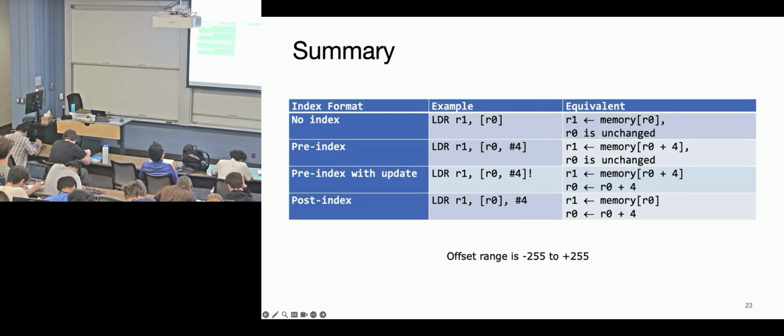Wait, this store instruction, he's gonna put the whole thing right back. Yeah, that's what I thought. So it's not gonna do anything, but it's gonna have to update, pre-indexing by 2. Memory. The next address. We run out of memory addresses. Watch out for that. It's gonna do pre-index and then it's also gonna increment, so this is gonna go to 9C.